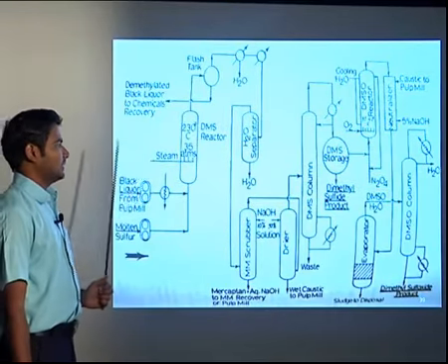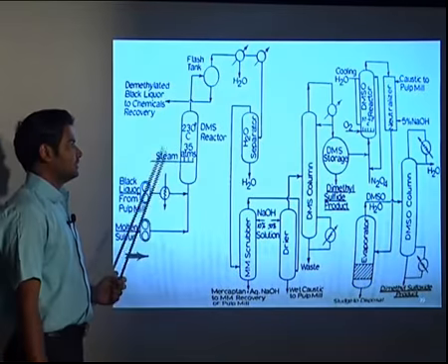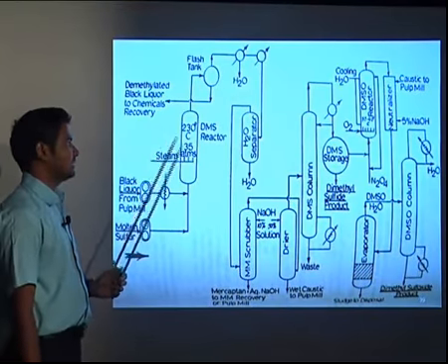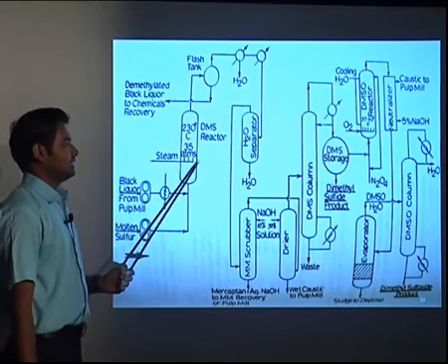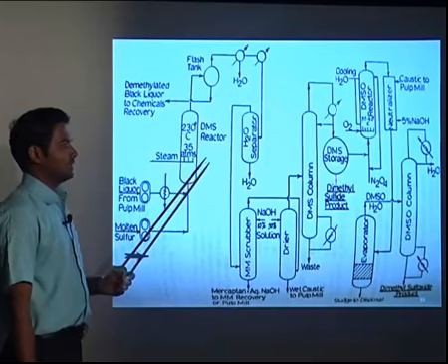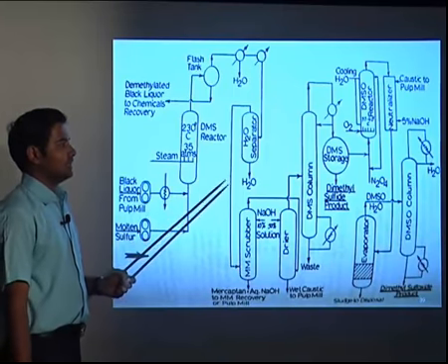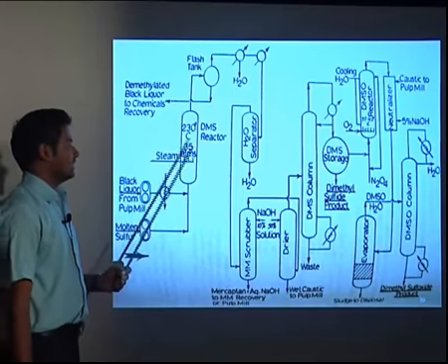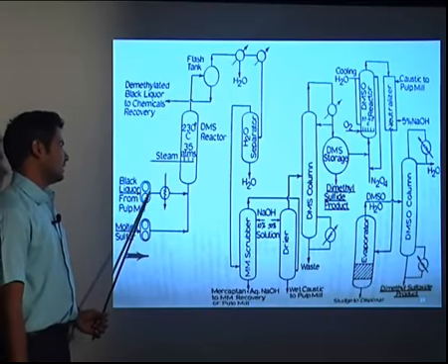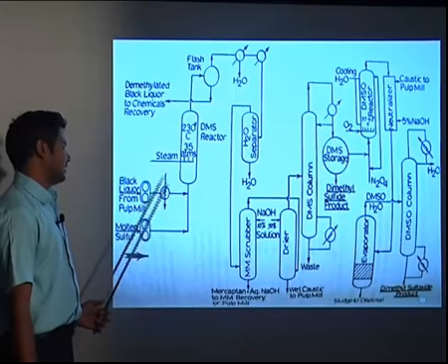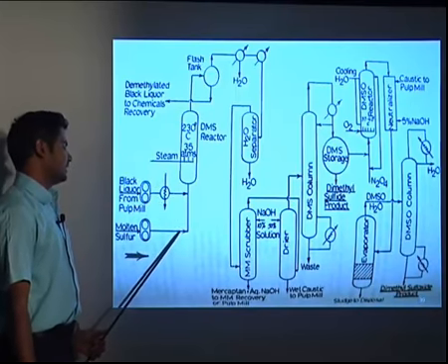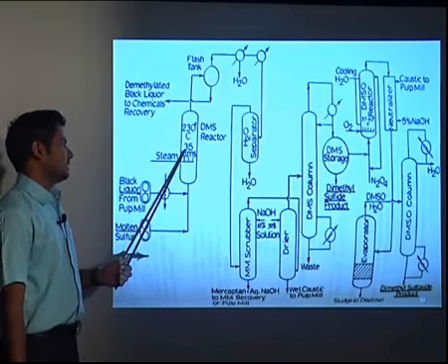So here we require the lignin. Lignin first, by reaction with sulfur, is converted into dimethyl sulfide, whereas the dimethyl sulfide, by reaction with N2O4, gives dimethyl sulfoxide, where N2O4 is required back. Here the black liquor which contains the lignin will come from the chemical recovery of the pulp mill industry, and the molten sulfur we are sending from the sulfur tank so that they will react over here.